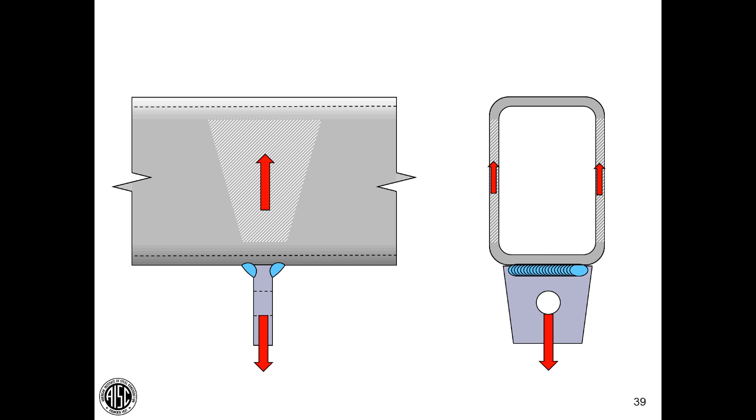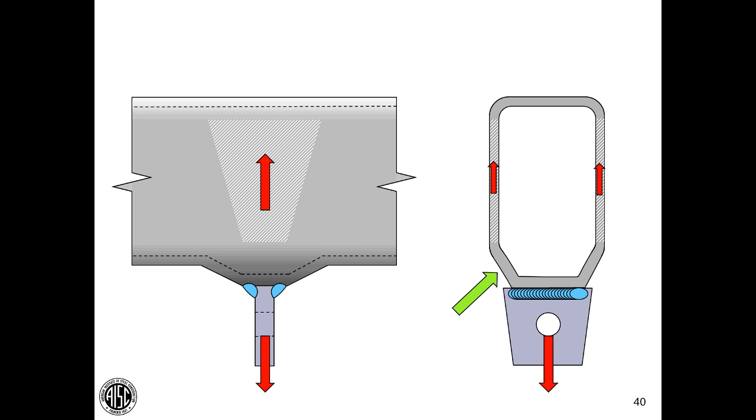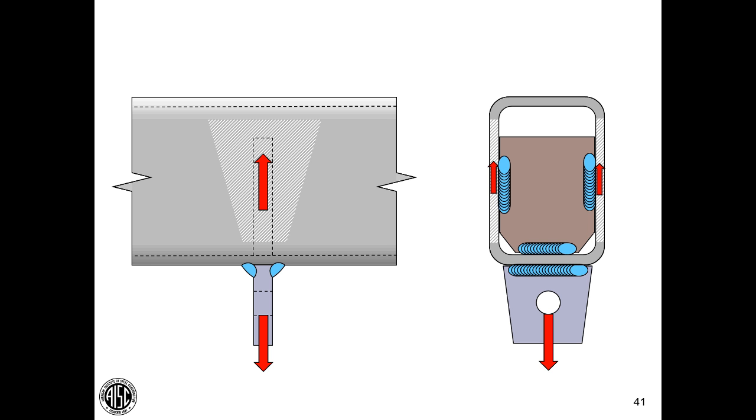The ends of those welds are going to have the highest stress, and of course they're right in the location of the stress riser at the end of that weld. The deformed state helps us see what's happening at that location. And again, we have straining at the toes and straining at the ends of those welds. A better solution than just rotating the lug would be to also add an internal diaphragm.